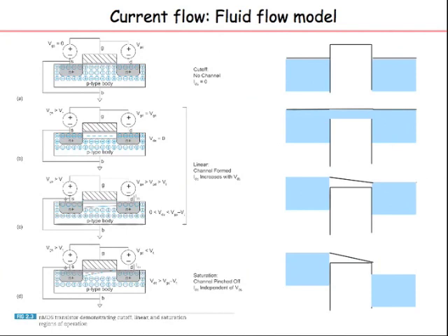So the quality of the connection between the source and drain is determined by the potential at the gate. The source and the drain are n plus, which means they have a lot of electrons. The channel is p-type, so there are not too many electrons. Under normal circumstances, the source and the drain cannot exchange carriers because there is a barrier. That is shown graphically on the right side, where you have two water tanks and a barrier between them. Water cannot flow from left to right.